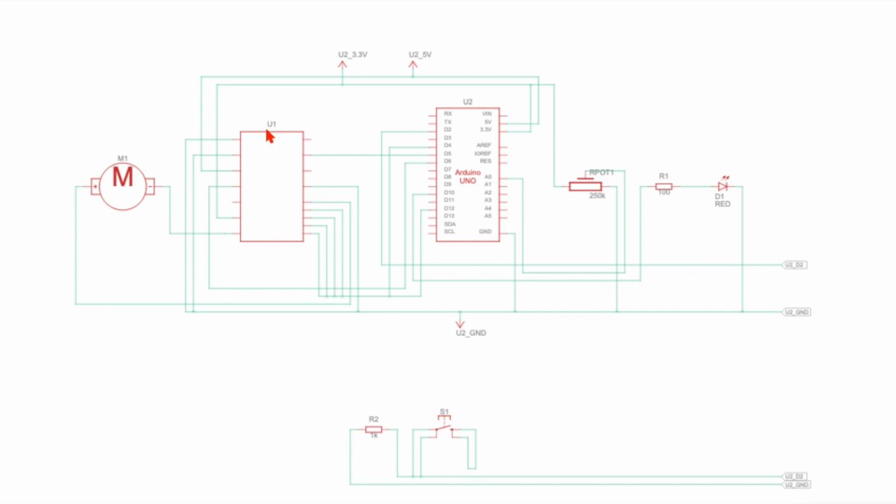So starting off with the motor drive, I'll start by showing the grounds. So this is the ground strip here on the board, and you can see it goes into the motor drive 3 times here, in through here, and in through here. And one of these is for the board itself, one of them is for the motor, and one of them is for the digital outputs that come from the Arduino.